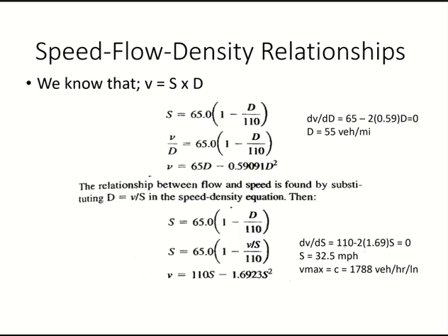Okay. Clear? There's another practice question. You will do this later on. But is the procedure clear or not? Okay. Now we come here. Again, this is the equation of a curve. And the curve is for rate of flow. When the equation reaches maximum, I reach capacity, right? And at capacity the slope should become 0. So I will take the derivative and put it equal to 0.